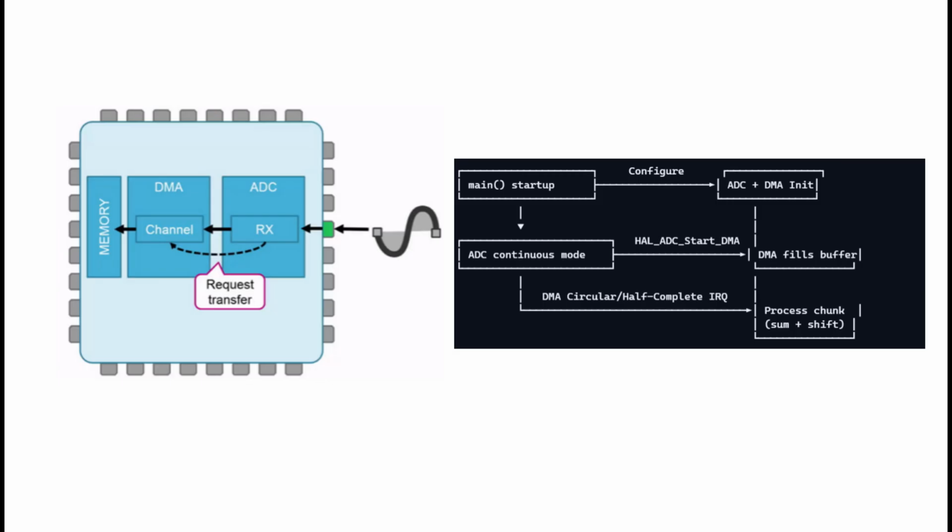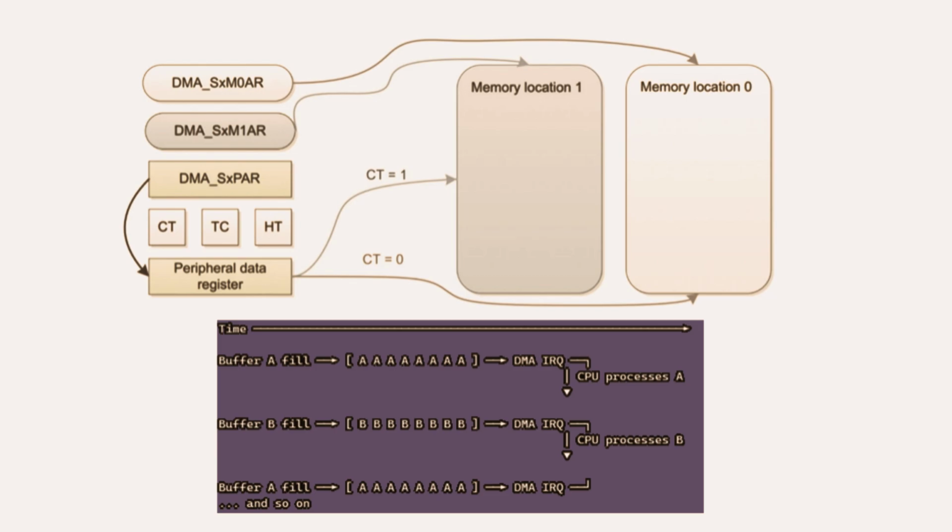Hardware oversampling. Nice. Okay, one more advanced technique you mentioned, especially for continuous high-speed stuff, this ping-pong buffer idea. Yes, the double buffer, or ping-pong strategy. This is a classic DMA technique used to maximize throughput and minimize latency when you need to continuously acquire and process ADC data streams without any gaps. It tackles a potential issue with single circular buffers. What happens when the CPU is busy processing the buffer just as the DMA wants to wrap around and overwrite the data the CPU is still reading?